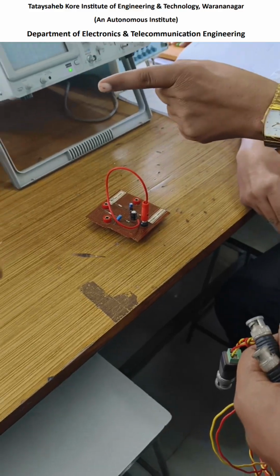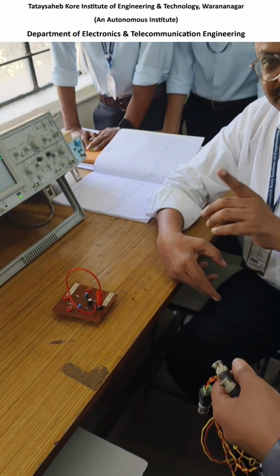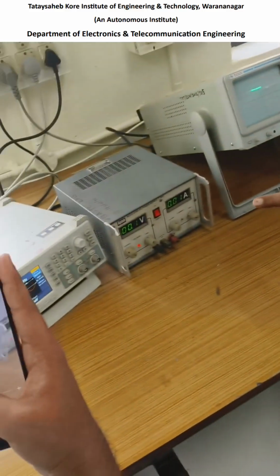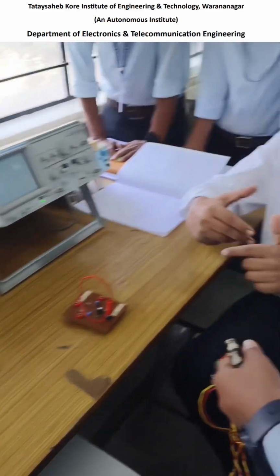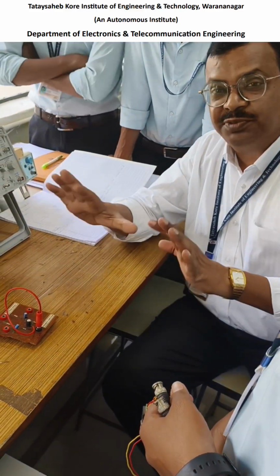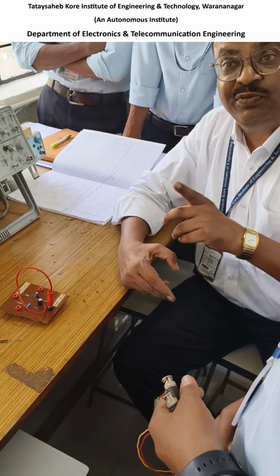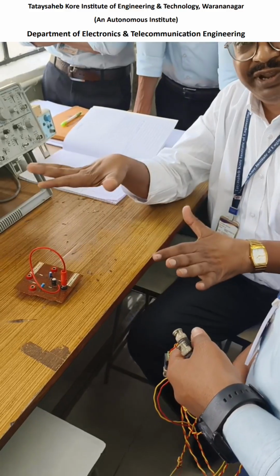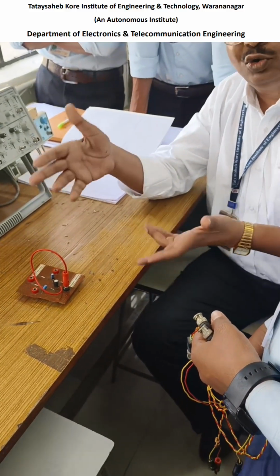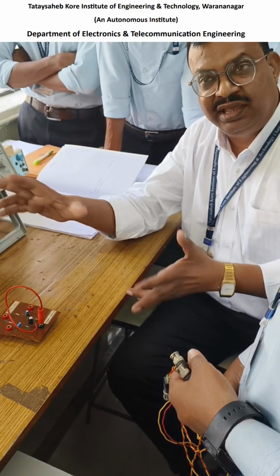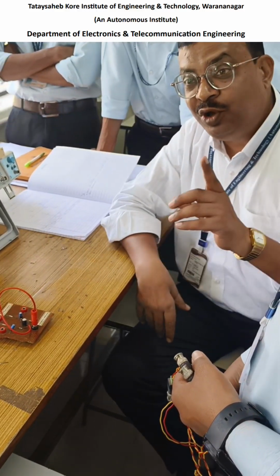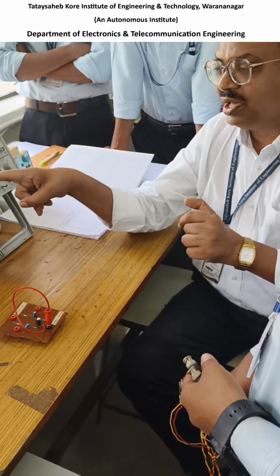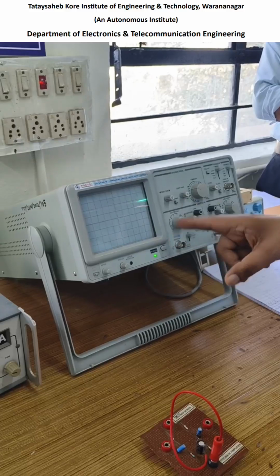What do you have to change? You have to change only the input frequency. That will start either from 20 Hz or 50 Hz. So whatever frequency change is there in the signal generator, that frequency you have to vary. You start from 50 Hz for example, and you reach up to 1.5 megahertz in steps. Simple steps. What are the steps? First 50 Hz, then 100 Hz, then 200 Hz, 500 Hz, 1K, 2K and so on up to 1.5 megahertz. For each input frequency, you note down the corresponding output voltage on the CRO.